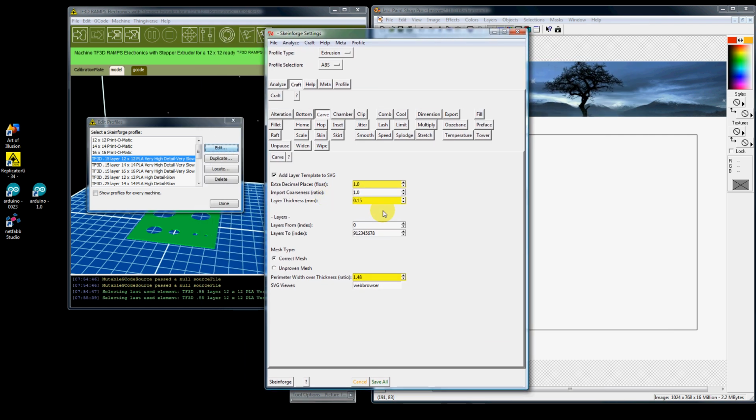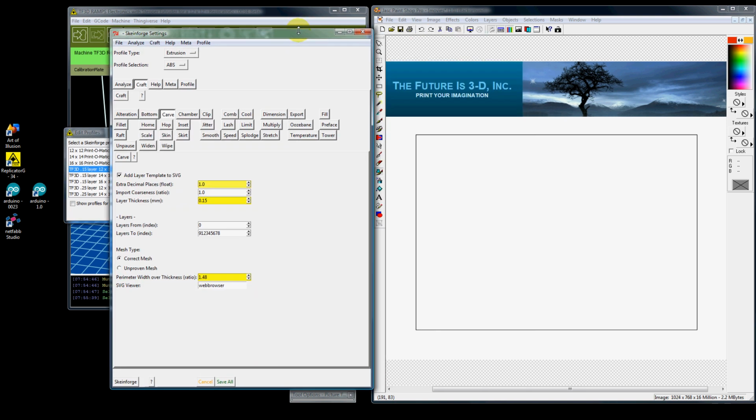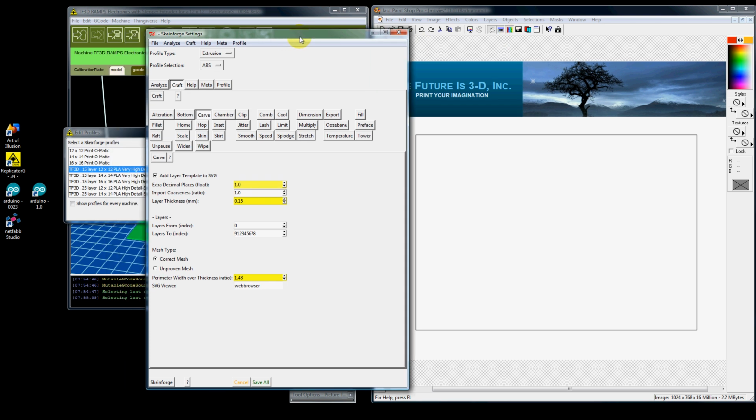Now we're using a 0.35 millimeter nozzle, so the highest I can get out of that is 0.55. As it comes out, the head slows down, I can get a little thicker, a little bit larger. So depending on what nozzle size you have, and we're going to have videos for how to adjust for your different nozzle sizes up to 1 millimeter in size.